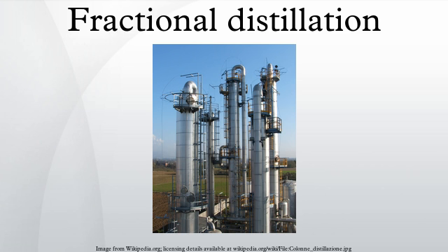The more reflux is provided for a given number of theoretical plates, the better the tower's separation of lower boiling materials from higher boiling materials. Alternatively, the more reflux provided for a given desired separation, the fewer theoretical plates are required. Fractional distillation is also used in air separation, producing liquid oxygen, liquid nitrogen, and highly concentrated argon. Distillation of chlorosilanes also enables the production of high-purity silicon for use as a semiconductor.